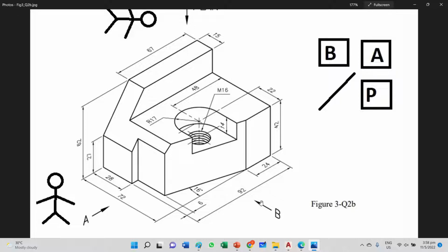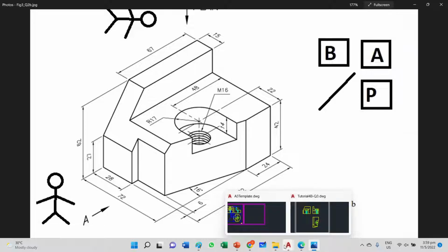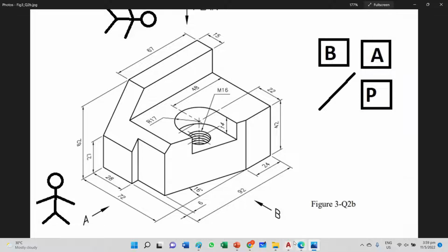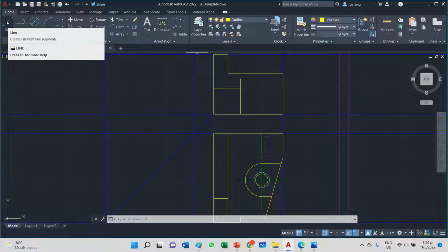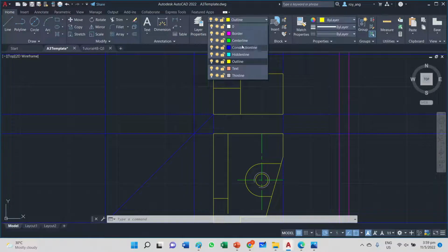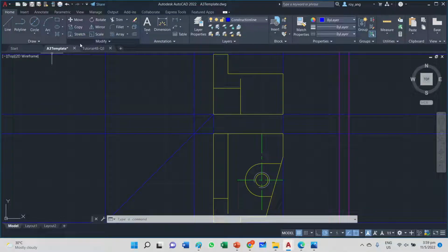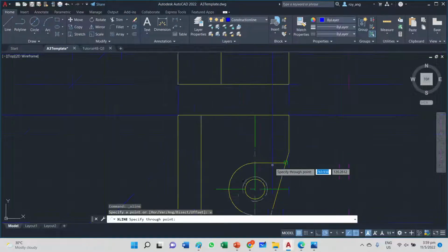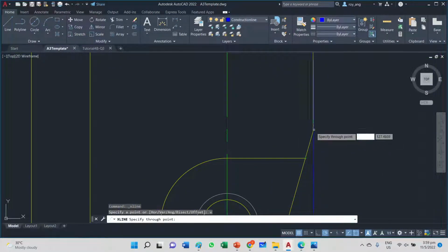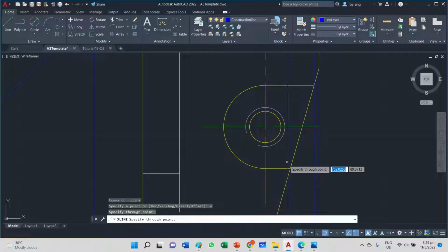So you'll see you want to copy the template across and then draw another drawing, but what happens is that the construction lines can end up messing up the other views and make it look quite complicated. So one way to manage it is you draw a giant rectangle, okay? It's an outline. Later on, you should delete that outline. Then you trim lines. I'm going to draw vertical construction lines and project, because then you trim. All points are very close to this, and I may accidentally project from this edge. So I want to make sure that I get the right trim point all across.